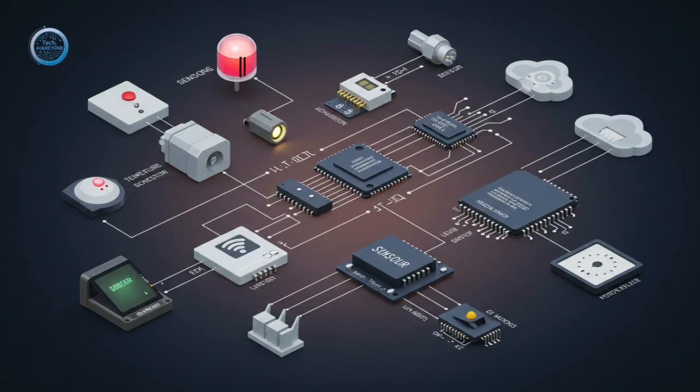So question 4, what are some of the different types of motors that are commonly used as actuators in IoT and robotics? Right. Motors are absolutely central, converting electrical energy into physical motion, countless applications. We generally encounter 3 main types in IoT and robotics. First, you have DC motors. These are the simplest kind, typically 2 wires. Apply voltage, they spin. You control the speed mainly by varying the voltage level. You find them everywhere, fans, toys, simple wheeled robots. Very cost-effective for basic continuous motion.